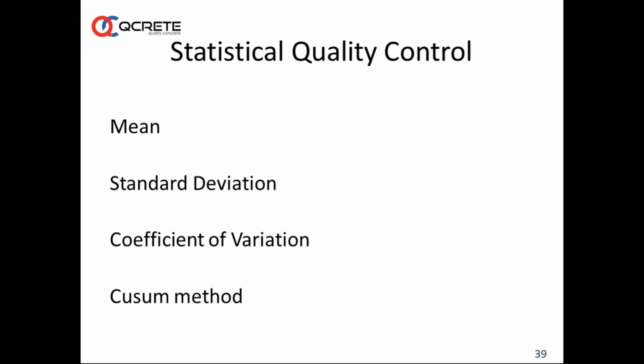Aggregates can contribute to the standard deviation, because the slumps will change if the fineness changes, especially the 150 microns and below 75 microns. If these fine particles in the fine sand or fine aggregate change drastically, it will lead to slump variations. For that, we need to increase the water content a little bit or something like that, and it will contribute to the strength deviations.